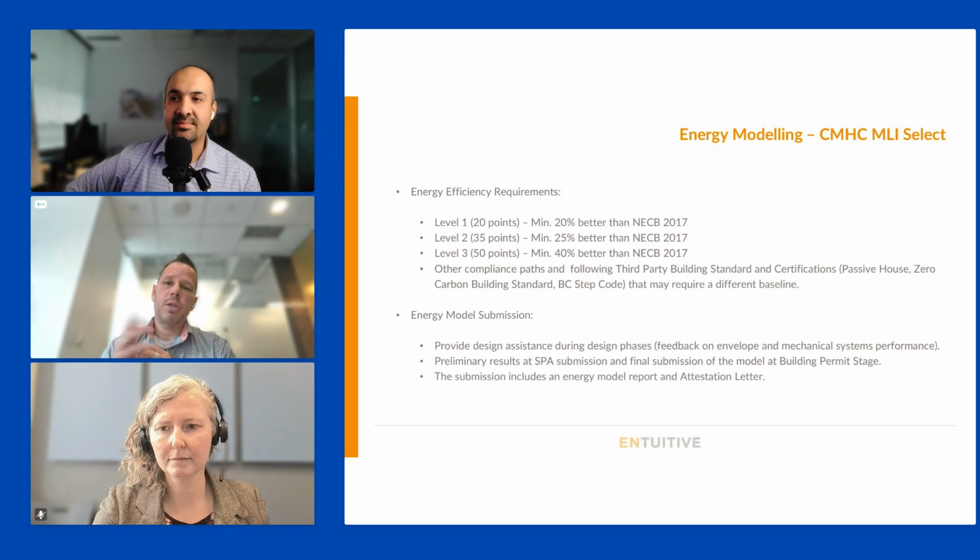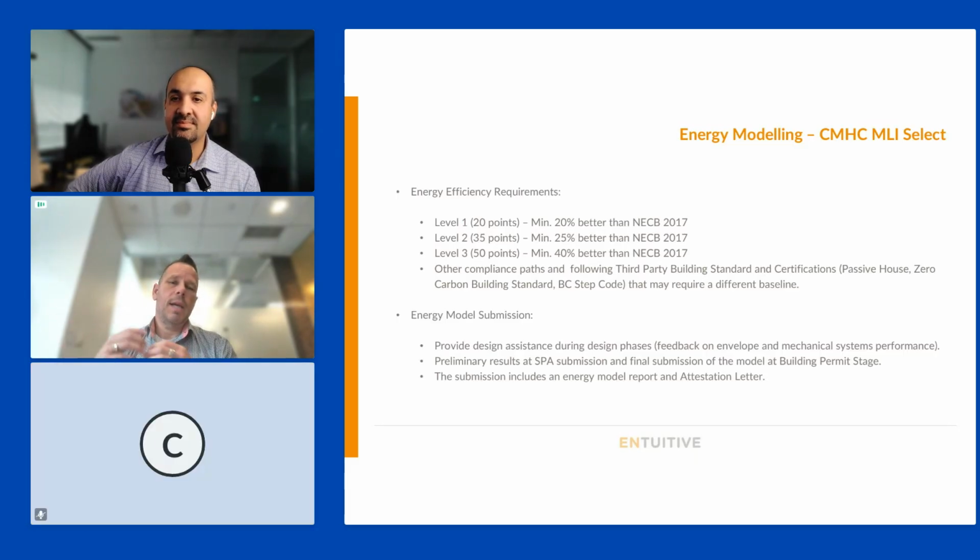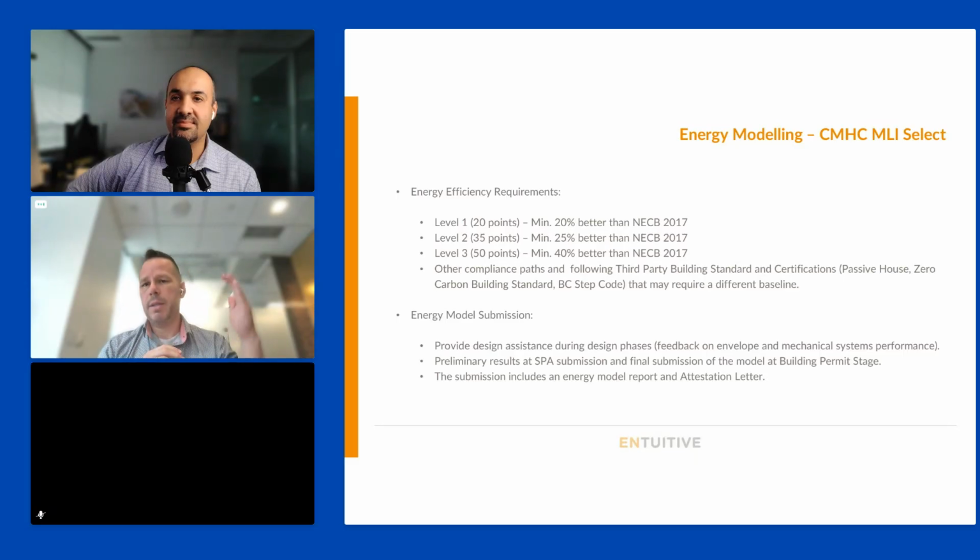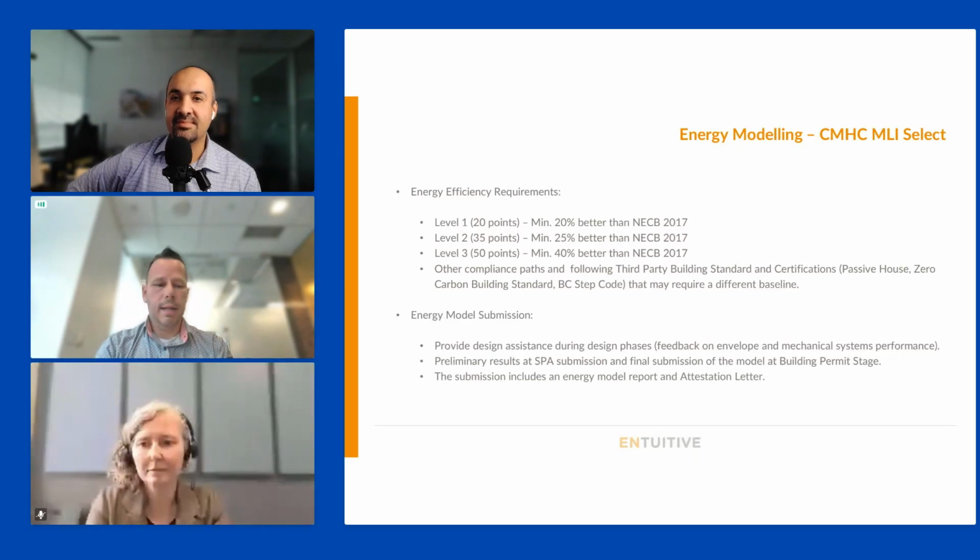And then it's an energy modeling report and an attestation letter. So it's basically saying, yes, we followed all the CMHC MLI Select requirements. We've done the modeling in accordance with those rules. Here are the targets that we're meeting. And that letter gets signed and submitted with the package. So that's generally the process for energy modeling.